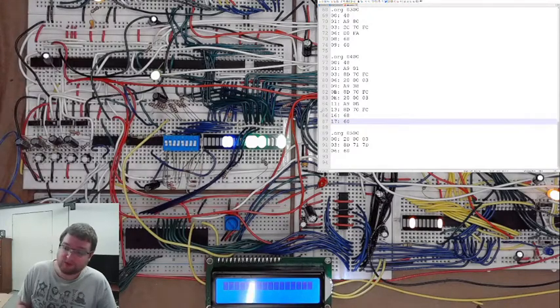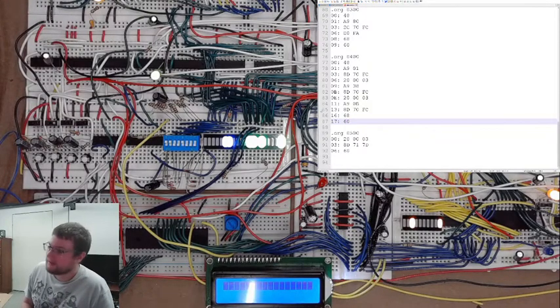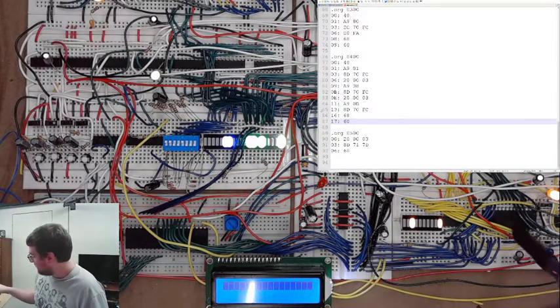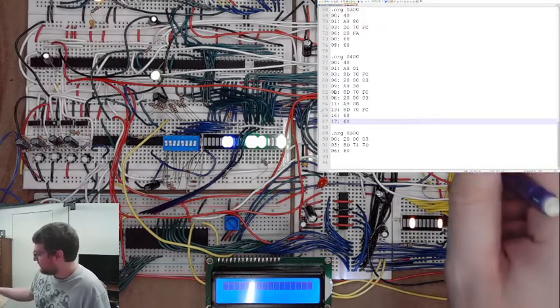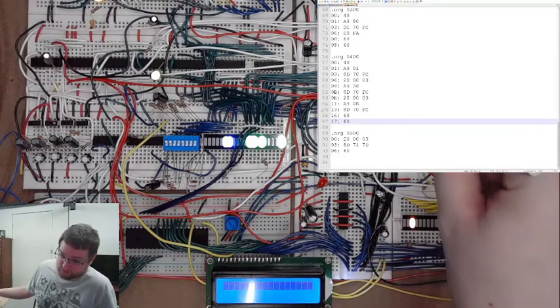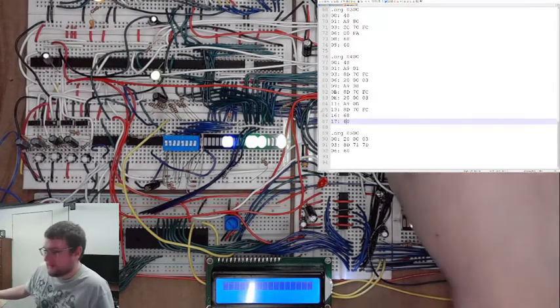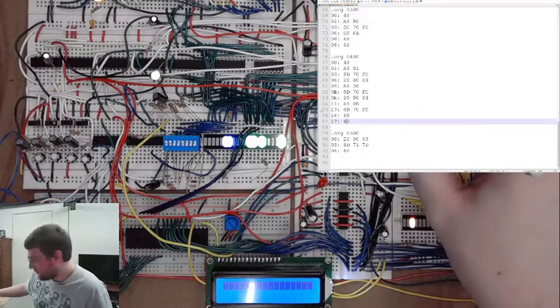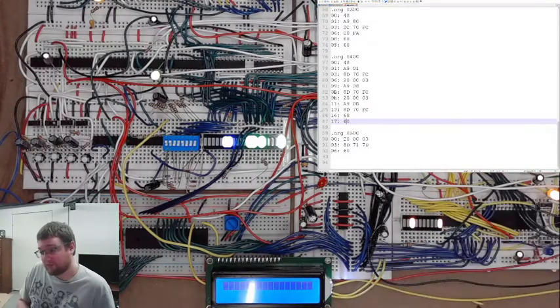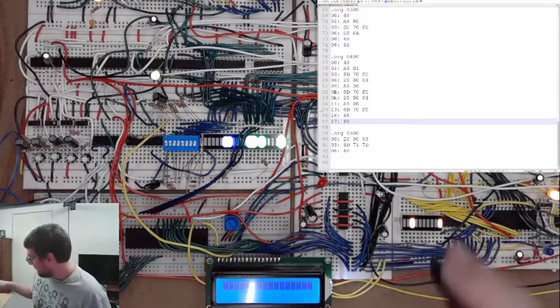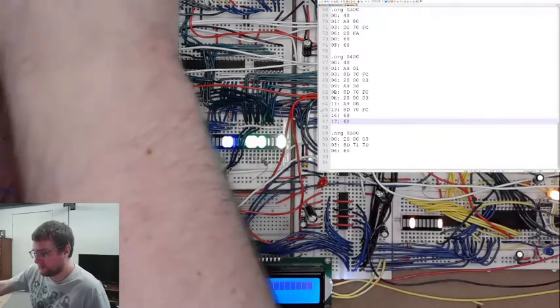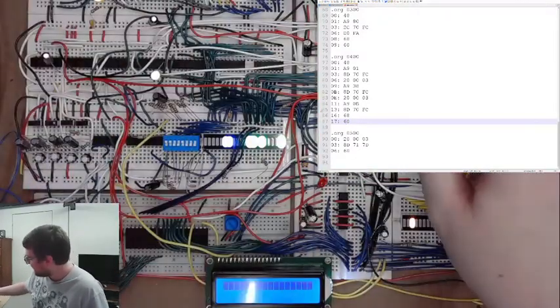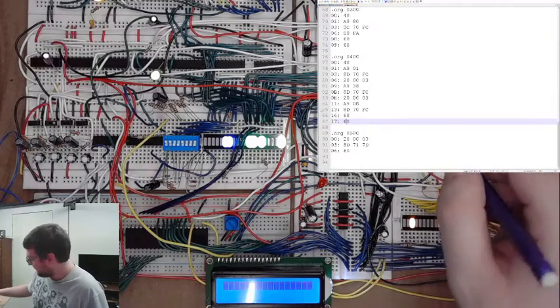Because then we don't have to fit our code into 32K, though we probably can fit our boot code into 32K. We can fit it into 64 because we can have the boot code load everything into the first 32K of RAM. We can then have that load everything into the last 32K of RAM. And suddenly we have a lot of RAM space. And then we can load everything from the SPI EEPROM into 64K of RAM.